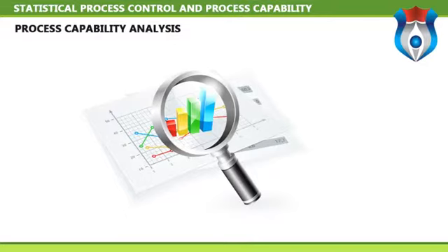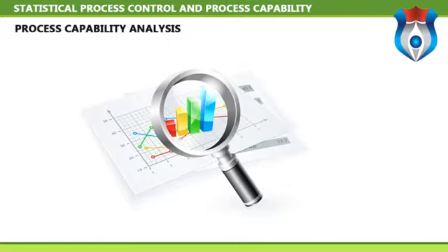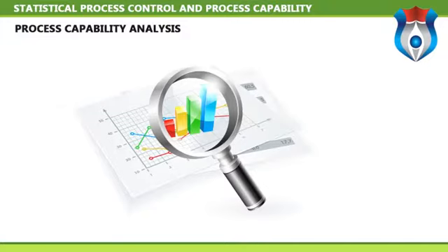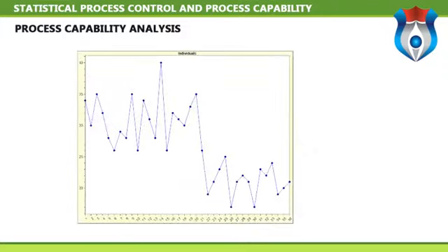Capability analysis is a set of calculations used to assess whether a system is statistically able to meet a set of specifications or requirements. To complete the calculations, a set of data is required, usually generated by a control chart. However, data can be collected specifically for this purpose. Specifications or requirements are the numerical values within which the system is expected to operate, that is, the minimum and maximum acceptable values. Occasionally, there is only one limit, a maximum or minimum.